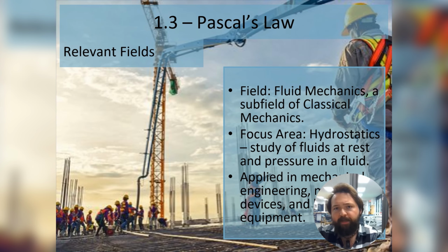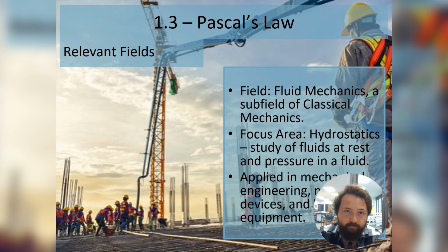In the field of fluid mechanics, which is a branch of classical mechanics, one important focus area is hydrostatics, the study of fluids at rest and the pressure within a fluid. Pascal's law falls under this area. It states that any change in pressure applied to a confined, incompressible fluid is transmitted undiminished in all directions throughout the fluid and to the walls of its container. This principle is widely applied in mechanical engineering, medical devices, heavy equipment, and many other common applications.